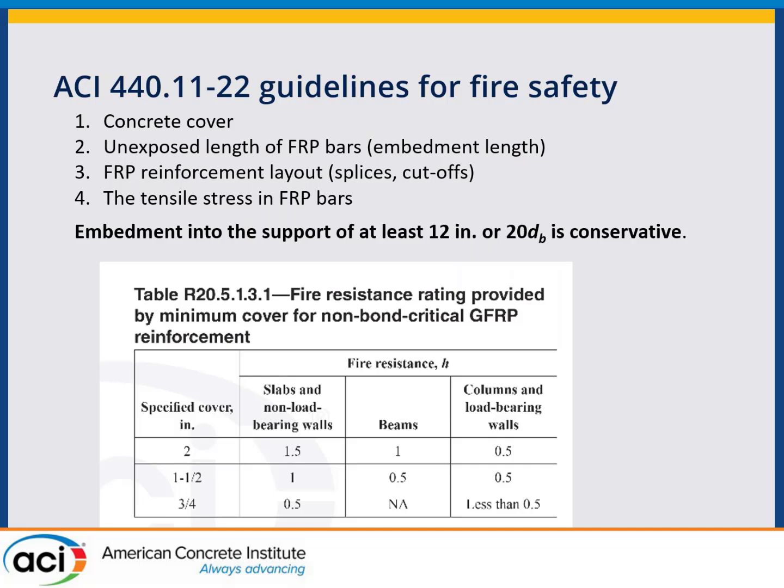So that's where we look to say, okay, well, how can we implement this into the codes? And so we said, well, let's say that we should have embedment into the support of basically a development length. And that's what we have here for the bars. The best thing to do would be not to splice bars where they might be exposed to fire and then embed into the support by 12 inches or 20 bar diameters, is basically what we're suggesting. And with that, it's suggesting with 1.5 inch cover that you would get a 1 hour fire resistance.